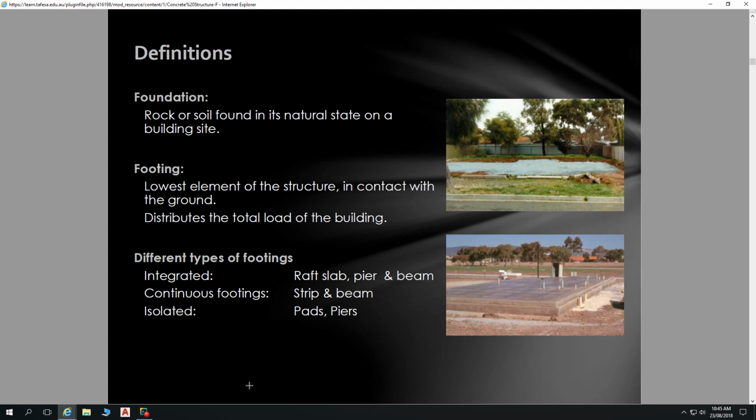So you can have a series of piers with a beam on top of that, and that provides you a structure. Now that might be elevated from the ground. It might be in the ground. Sometimes we use pier and beam or pier and slab to get loads transferred down to a reliable base.